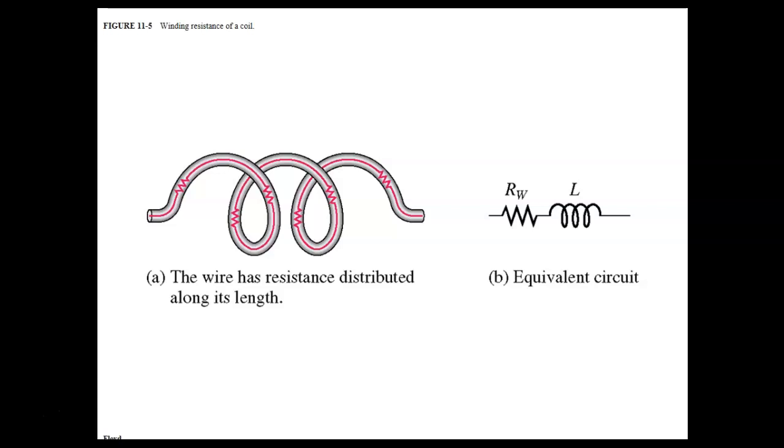If you've got some of these big old woofers, they'll have almost no resistance. If you measure the resistance across that thing, it'll be about six ohms. If you put 12 volts across 6 ohms, you understand that's going to be 2 amps across that thing. But we're not putting DC on them, we're putting AC on them. So audio is AC.